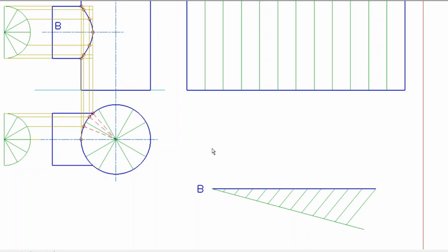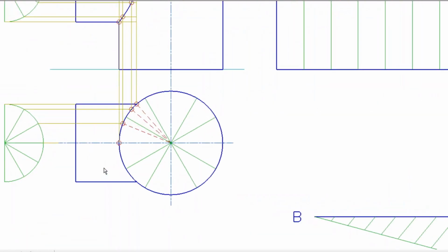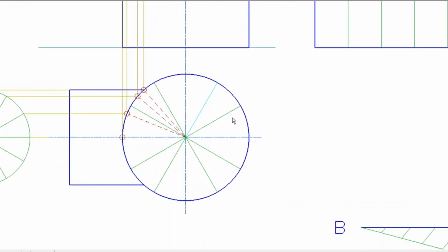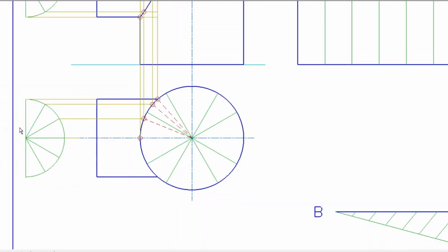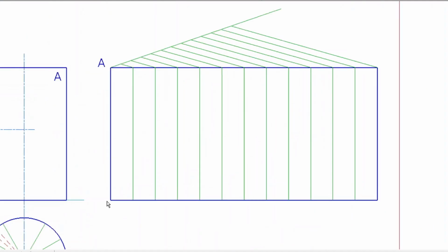Now in both cases you have to divide the development into 12 equal parts. The reason for that is because in the top view we divide our cylinders, both of them, into 12. So that's why we have this half circle here for the branch, and this is also why we divide the main into 12 segments. The center also acts as segment lines. So there's 1, 2, 3, 4, 5, 6, 7, 8, 9, 10, 11, 12 of them. Now, some students will take that length, which is 151, divide it by 12 on the calculator, and simply mark that down.